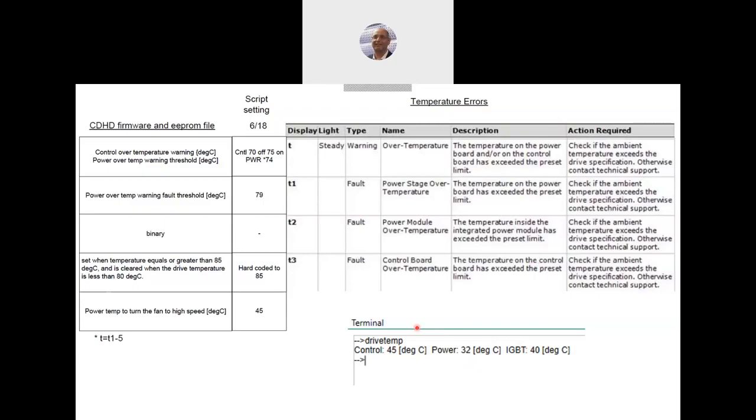Usually for the temperature of the servo drive, the first warning is at 60 degrees. Then at 80 degrees, usually we stop the drive. And we don't allow the heatsink of the servo drive to be more than 100 degrees. So it's very simple to remember: the servo drive must be below 100 and work below 80, where the motor can work up to 150. So these are the areas where we work regarding the temperature.